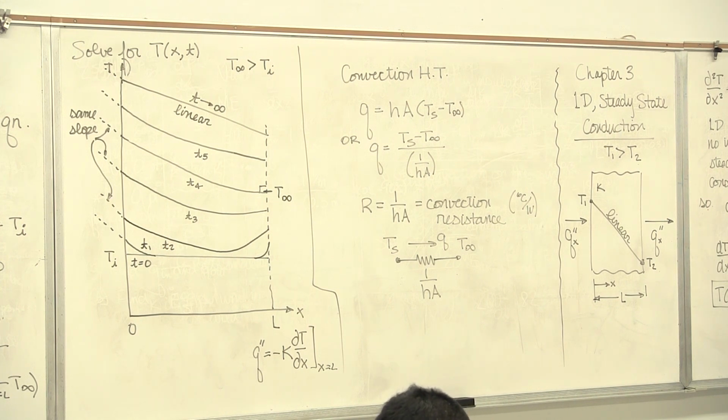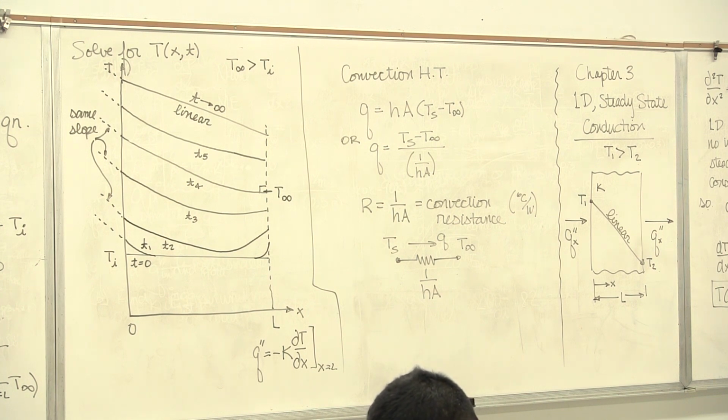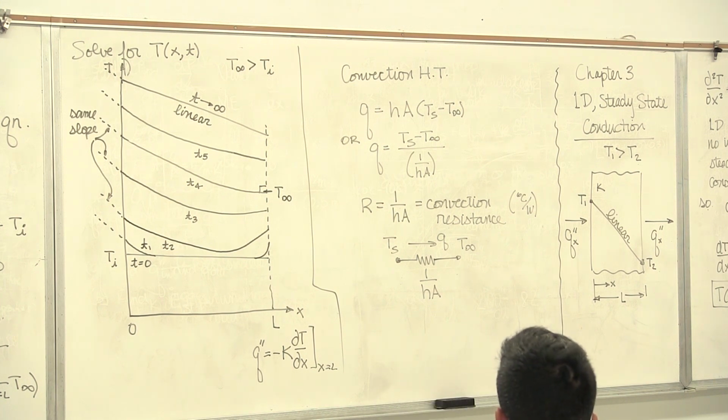These things luckily make some common sense. If I want to insulate this room from that hall, here are my choices. What do I want to do? If you insulate it, I want to have a large value of that resistance, because a large value of that resistance means a small value of Q. I want to make resistance large to insulate this room from the hall side. The obvious way to make it a high resistance is to make the wall thicker, and that's common sense. I'll double the thickness of the wall.